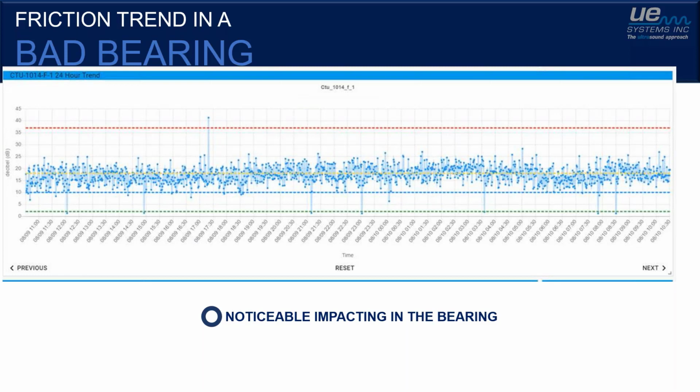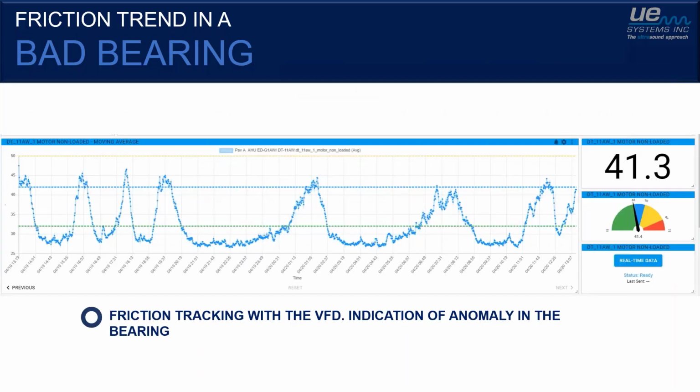You can look at this and just say, there is a lot of noise, a lot of impacting happening in this bearing, right? You don't need to do anything else. You don't need to stand on your left foot, bite your tongue to the right to make some sense of this data. This is generally an unhealthy bearing. Is it going to fail tomorrow? Unlikely. Will lubrication restore this? It might. And that's where I'd recommend going out there and applying a little bit of grease to see what happens if you can reduce some of this impacting and drop that friction.